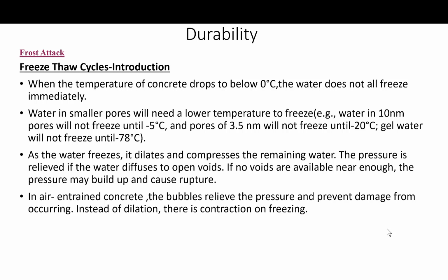So when saturated concrete is cooled below 0 degrees Celsius, immediate freezing of the water in the cement paste does not occur. It must be remembered that the paste contains a wide spectrum of pore sizes, and it can be shown thermodynamically that water in capillary pores will not freeze until the temperature is lowered below zero by an amount that depends on the diameter of the pore, or more accurately on the diameter of the neck of the pore.